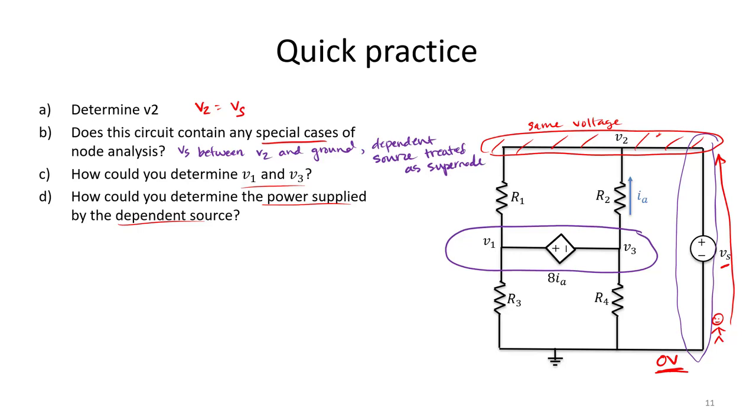Okay, so our next question. How could we determine V1 and V3? Think about that for a moment. Well, what should we do with supernodes? Notice if this whole thing is a supernode, we can apply Kirchhoff's current law to our supernode.